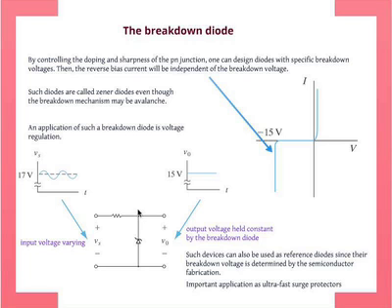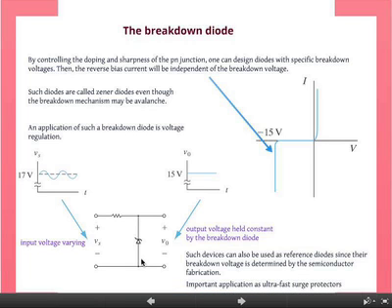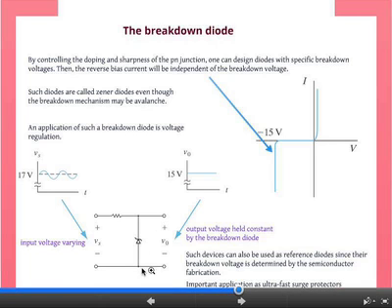And you can do that with this very simple circuit as shown here, which basically has a resistor and a breakdown diode. And the nice thing is that in the breakdown diode, the voltage is essentially fixed by the materials, whatever you decide in your junction, basically your doping. Of course, it will also depend on your voltage ranges and so on, but you can design for it. So you have a very fixed voltage drop that comes across here independent of the current.